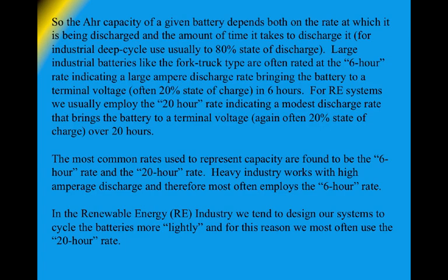Now, in renewable energy systems, we are discharging more lightly because, in fact, we're going to be charging more lightly. Our renewable energy sources don't come in at 120 amps for 6 hours just to get that 720 amp hours back into the battery. Our sun comes up and it starts shining at a diffuse rate, with a small amount of amperage. It builds through the day to a higher amount of amperage, and then it declines. And so we're planning for more light cycling of our batteries, both on the discharge side, primarily because we're going to be light charging on the charge side.